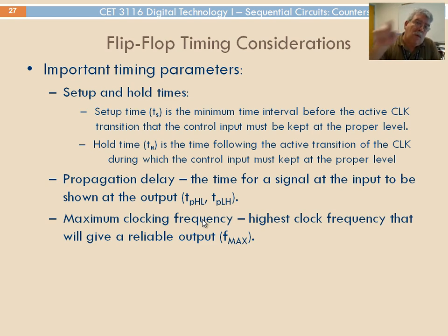If you remember, we did a feedback with an inverter, and we deduced the basic expression for the maximum frequency that corresponds to the minimum clock period. In general, that is a parameter that is also given in the specs of the flip-flops.